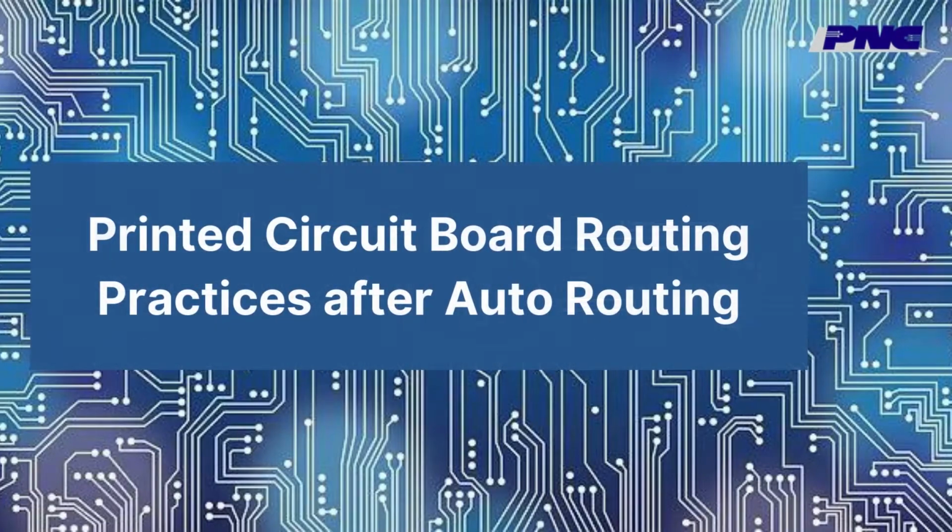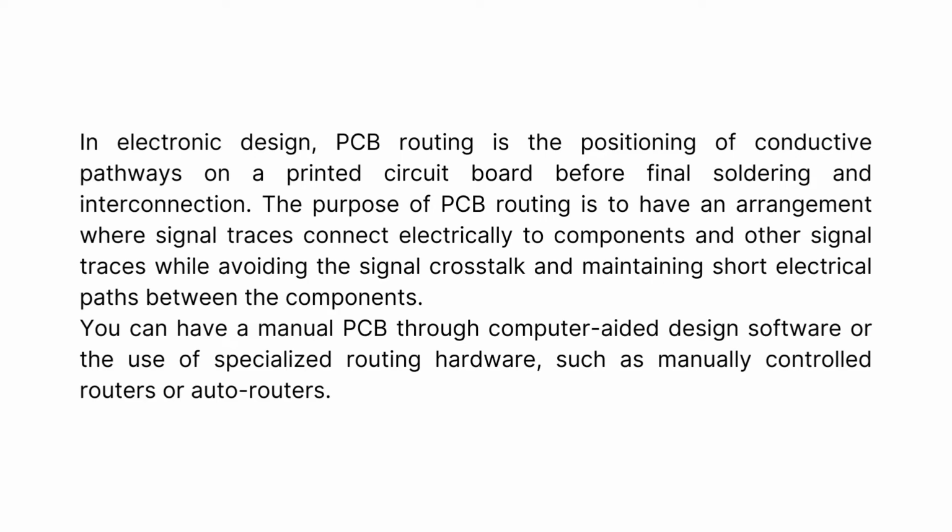Printed circuit board routing practices. After auto-routing in electronic design, PCB routing is the positioning of conductive pathways on a printed circuit board before final soldering and interconnection. The purpose of PCB routing is to have an arrangement where signal traces connect electrically to components and other signal traces while avoiding signal crosstalk and maintaining short electrical paths between the components.